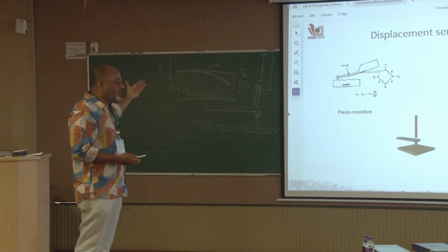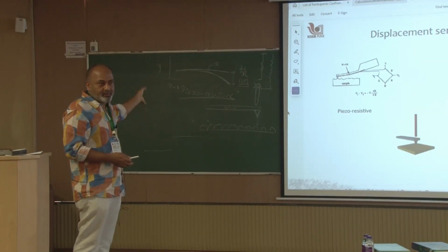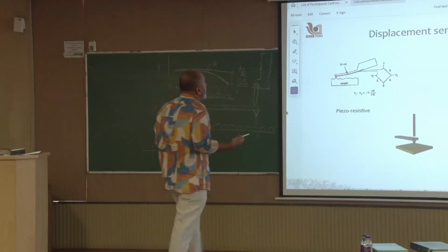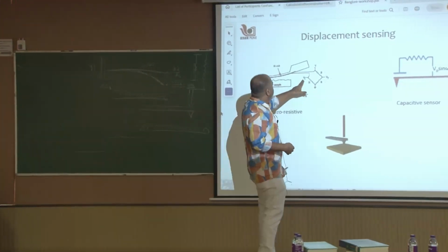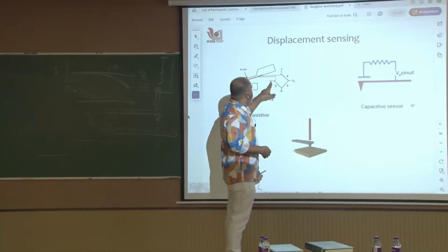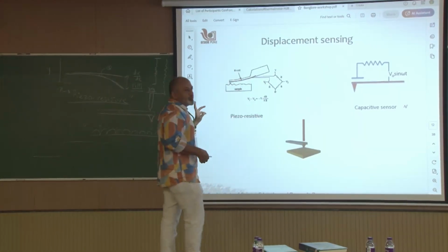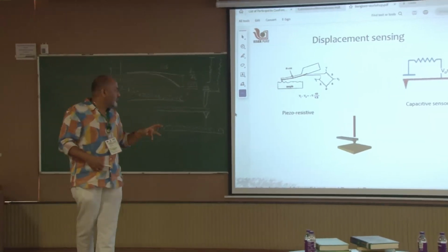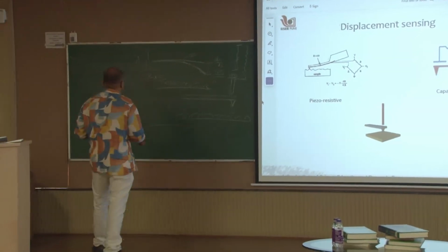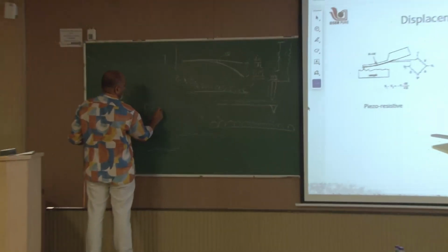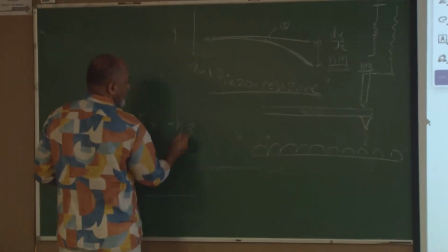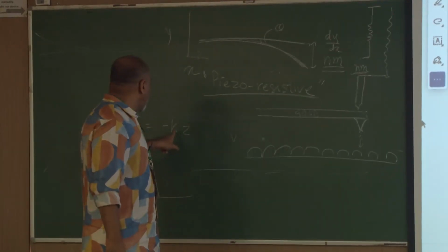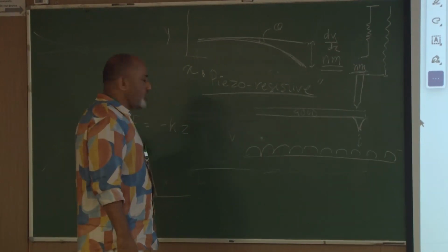So still the question remains, how do you calibrate this? For instance, if this is the voltage drop between these two terminals, V1 minus V2, what drop corresponds to what bending, and then that bending through this equation, Z, right? That is the bending. So how much is that? And then if you know the force constant, then you know the force.